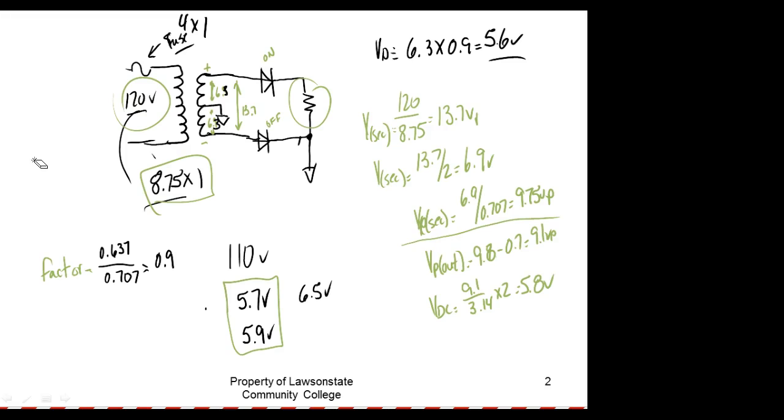And a lot of times your industrial transformers, they'll dip the whole transformer in wax to try to seal those wires in there and keep them from moving. Because if they sit in there and vibrate, what's eventually going to happen? It's going to wear that little thing out. So that's one of the biggest problems we have with transformers, winding shorts. If you have a winding short, then the turns ratio of the transformer changes, right?